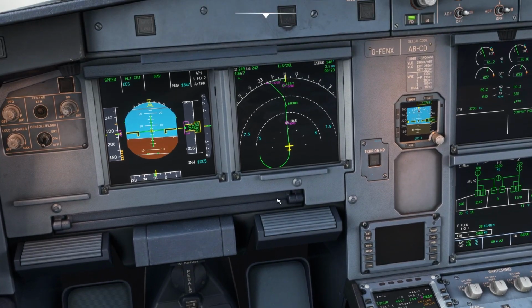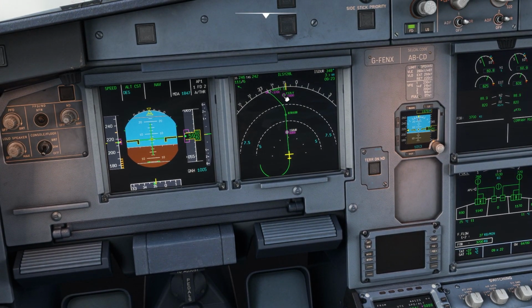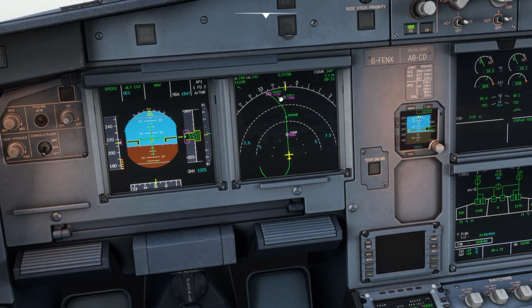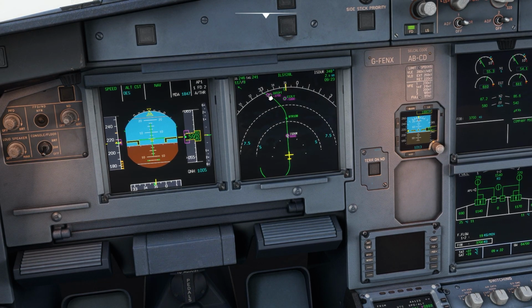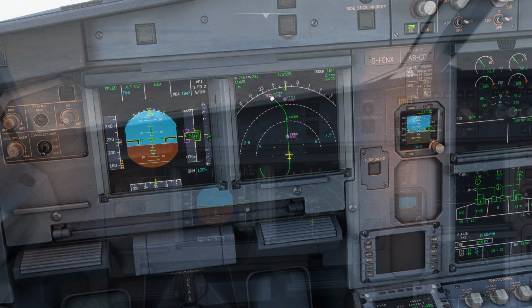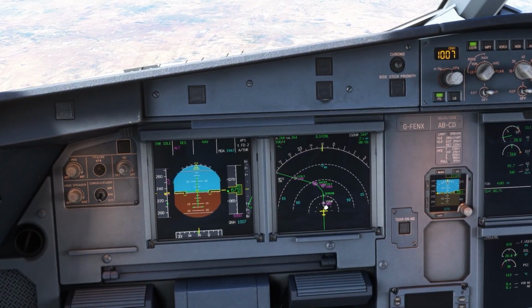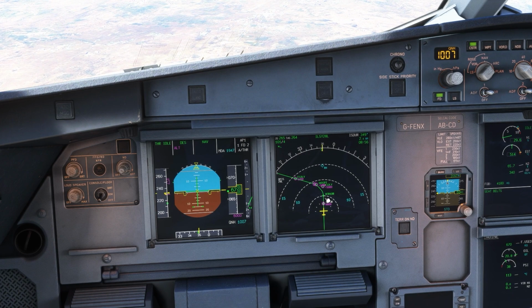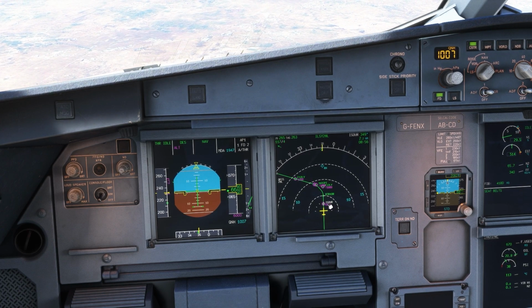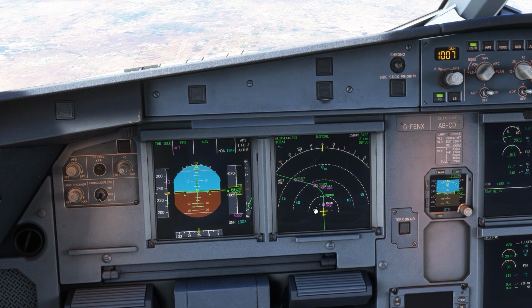And after this point, the plane will again descend, because at this point you should be at plus 5,000 feet, and over here plus 3,700 feet. And this is at the deceleration point. We'll be soon passing ISDO, then BTR 108, then a left turn, then I will activate the approach.